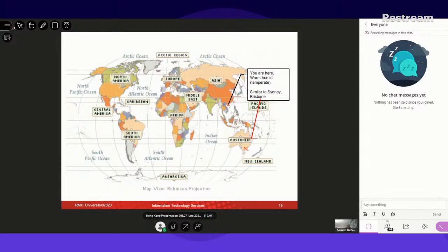Say for an example, in Australia, we try to plan our house so that most of the daytime living spaces are facing north. But if you go to Canada, it will be the other way around. If I go to Canada and if I design a home, I will look for most of the daytime living to be located on the south side boundary, and in Australia it's the other way.